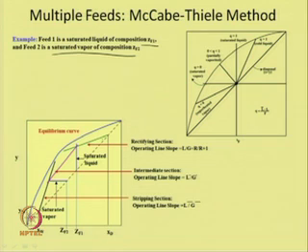If we draw the operating line for the rectifying section, this is the ZF1 which has composition ZF1, and with a saturated liquid if we plot with a slope of 1, then it will intersect the stripping section line and the starting point of the operating line in the intermediate section. Similarly, it would intersect the other feed points between stripping section and slope of the Q line of the other feed, feed 2 ZF2, which is a saturated vapor, which intersects over here.